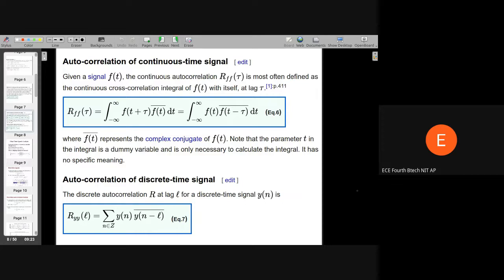This deterministic function has certain very important properties. If you put minus L instead of L, the output will remain the same. So this autocorrelation function is a symmetric function. You don't need to figure out negative lags; you figure out positive lags, and you automatically know what the negative lags are. Using this autocorrelation function, we can devise a short time analysis of speech method to determine pitch. We discussed that.